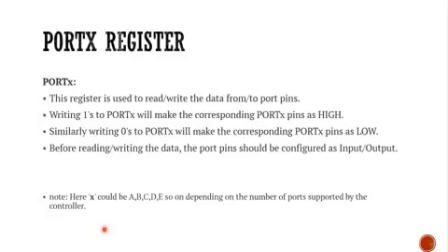Okay. And then the flow, like the previously drawn flow, after you have properly set the value, whether you want to set it as input or output, then you can proceed to writing or reading to your port. So this is the port that we use, port X. It may refer to either A, B, C, D, or E. Okay, so we use this port if we want to write or read. Okay, value coming or going out from that particular port or bit.